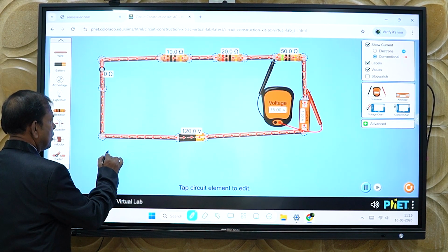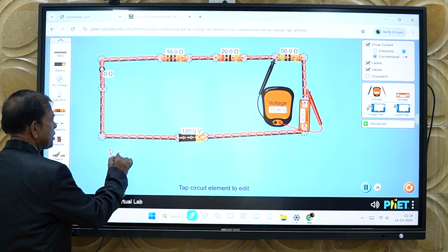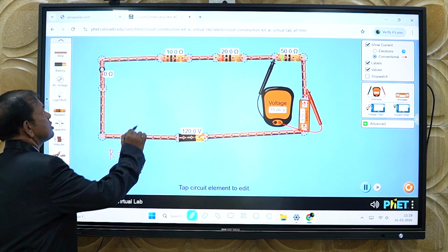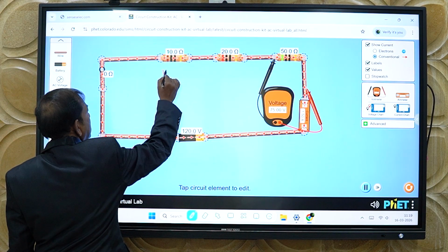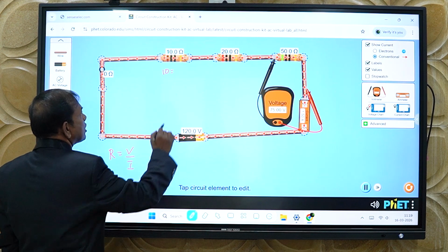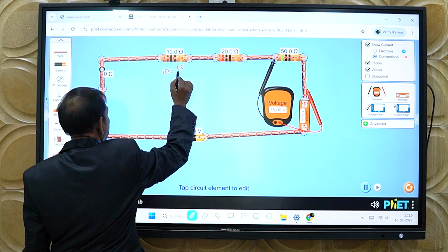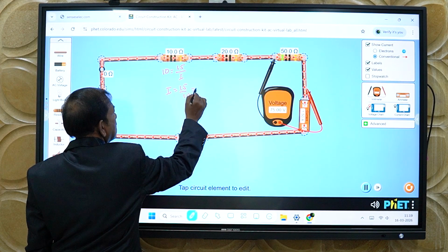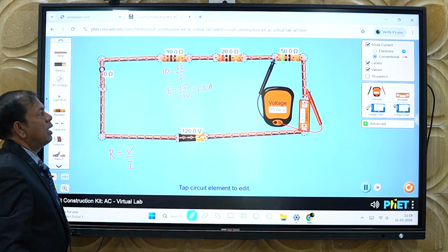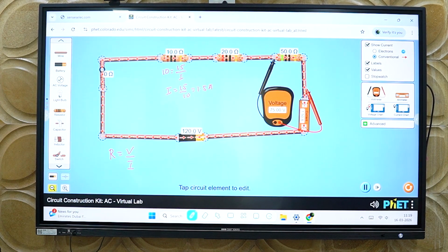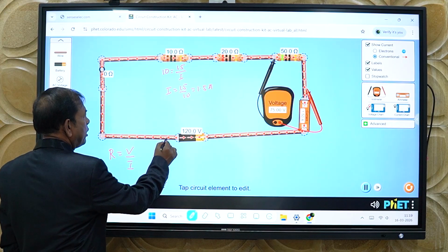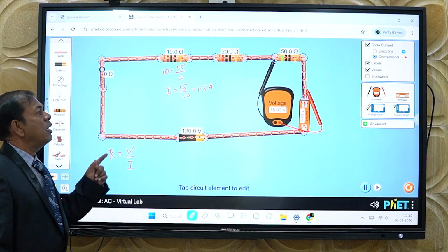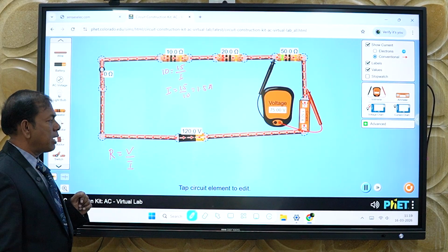Now in IGCSE we have learned that resistance is basically potential difference upon the current. Now you can talk about this resistance here. Let me apply here. Resistance is 10 here, and what is the potential difference across this? 15 divided by the current here, and that current is 15 divided by 10, that gives us 1.5 ampere, and that current remains same everywhere, because you need to understand in terms of electron. If one electron is getting pushed, only then the other electron will move. That's why current in the entire circuit remains same.